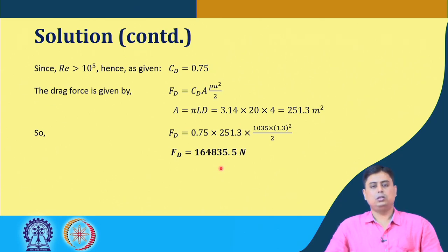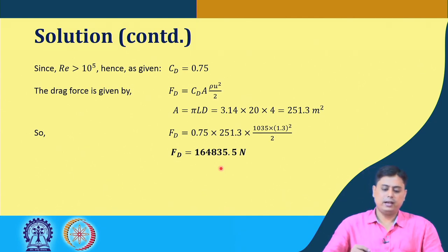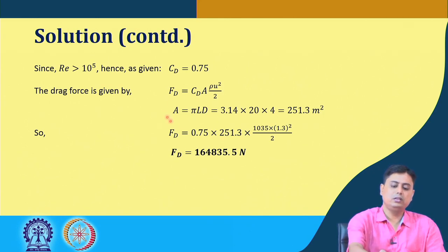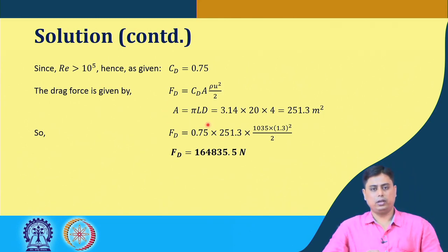Okay. So, we have to now calculate the drag force, and for that the area on which it is acting. Now, here the area is pi L d, or if d is 2 r, you can consider 2 pi r h, which is the surface area. Okay. So, drag is acting on this. So, if we consider this is the skin drag. So, now you can understand that since we have calculated in this way, how the particle is flowing.